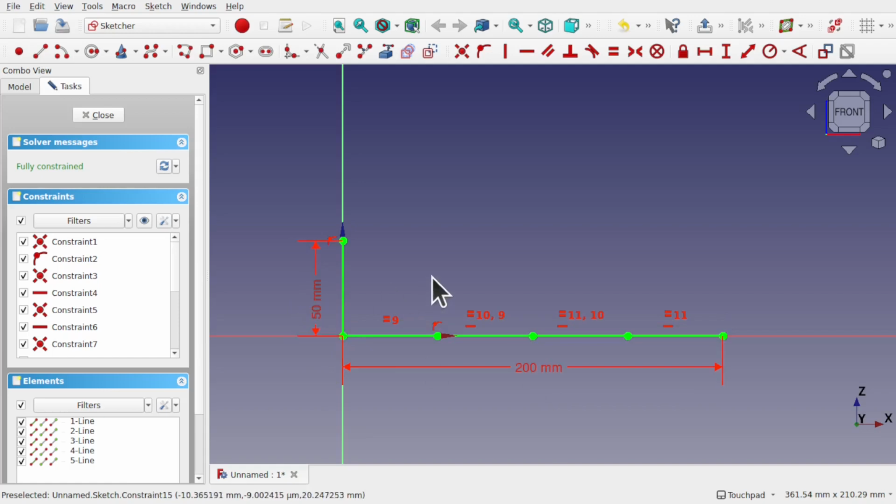Let's add a number of points to go along here. So these points will allow us to connect up to that B-spline and also use constraints against the B-spline. I'm going to place a point going across this way. So we're going to place 4 points going across here. Let's hit escape and we'll use this point and use the vertical constraint that keeps them in line.